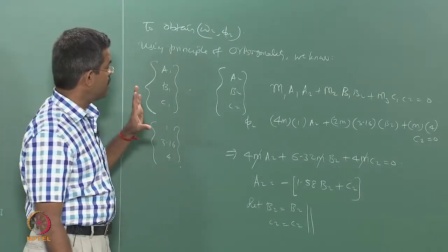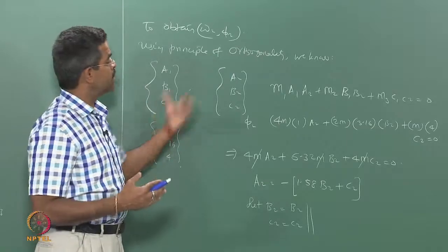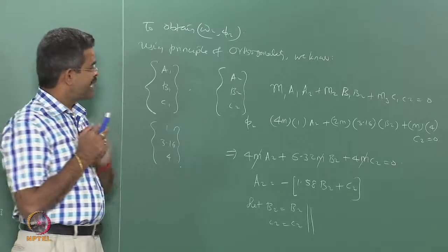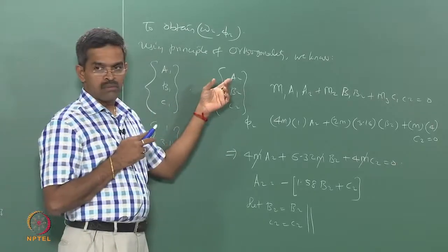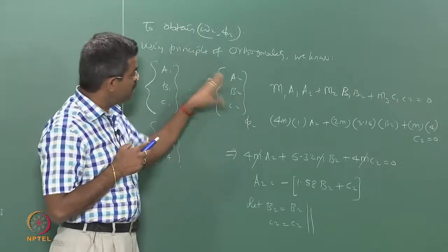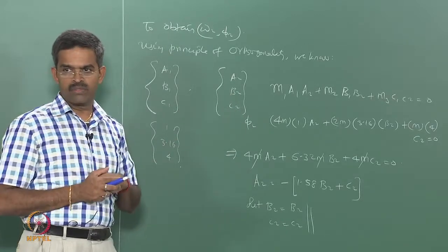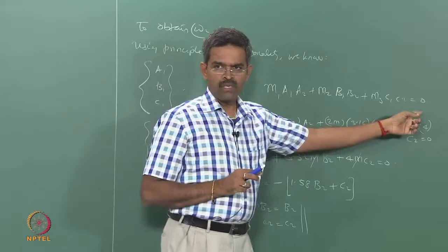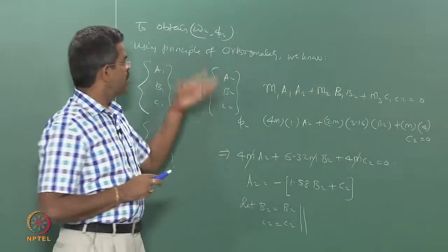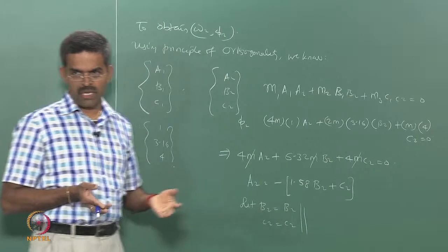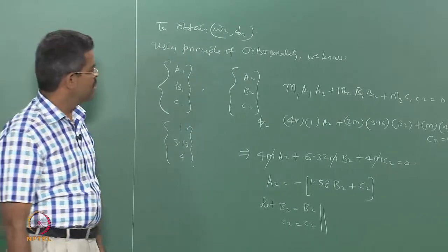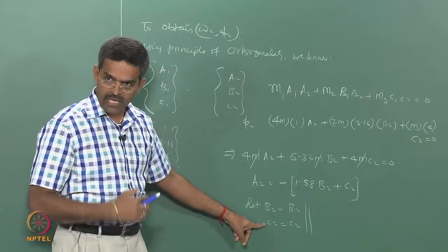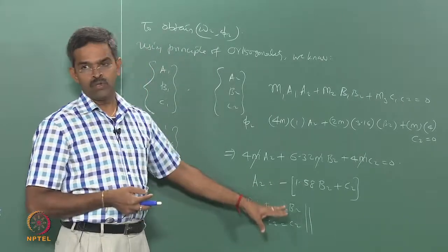Mode shape is nothing but the relative displacement of each mass position for a given frequency of vibration. They are not unique. If I know the proportion, I can find the remaining b2 and c2. So, I have only one equation and 3 unknowns, that is a2, b2 and c2. So, it is very interesting, I cannot solve this problem. Therefore, I have found one equation. The second and third equations I am generating myself, saying that let b2 be b2 and c2 be c2.